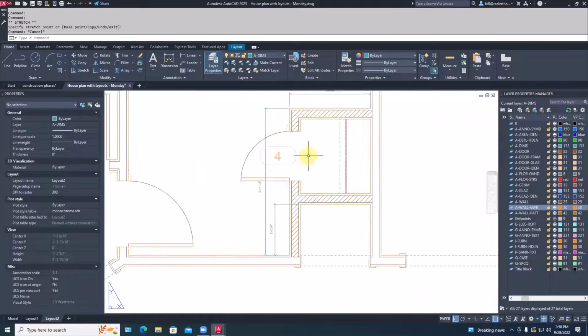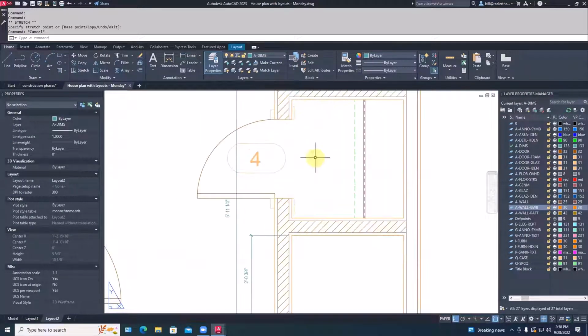But it would be nice to say that I want the door centered in the closet. I don't want to have to give them a whole lot of picky dimensions. So what I might just do is, we know the door width already from the door schedule. Door number 4 already has a width that's specified in there. So we might just set up two dimensions, and we're just going to say for them equal. I don't know what they are, 7 3/8, I don't know. I just like them to be the same.